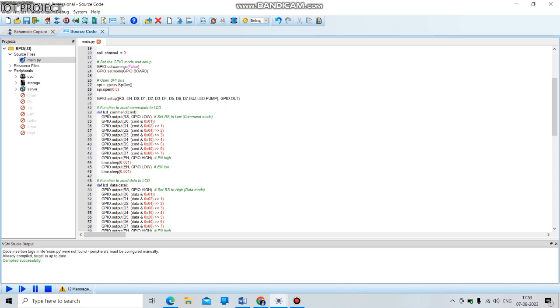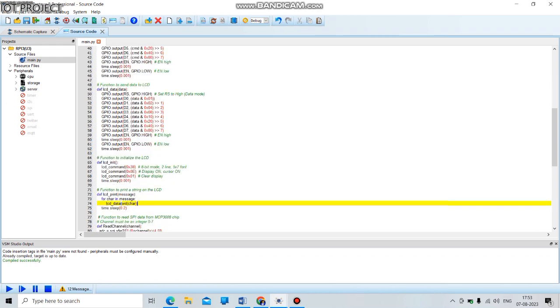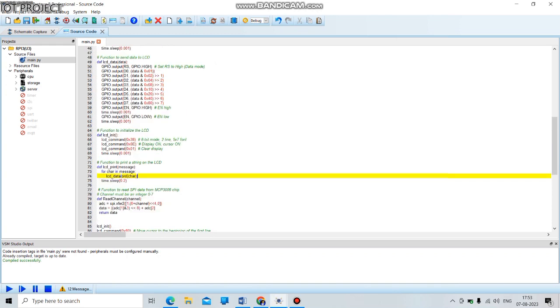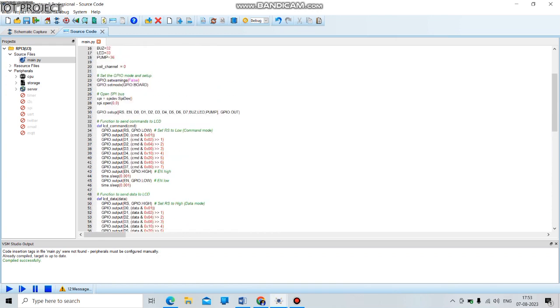So it checks whether this command mode is equal to 0x80. Okay, so we know that in 0x80 the first pin goes to high, because in the 8-bit mode the most significant bit goes to high. So here we have to use the AND operation. What is the use of the AND operation? The AND operation helps me mask a particular bit. So if I have to mask a particular bit, then we have to access the most significant bit of the CMD.